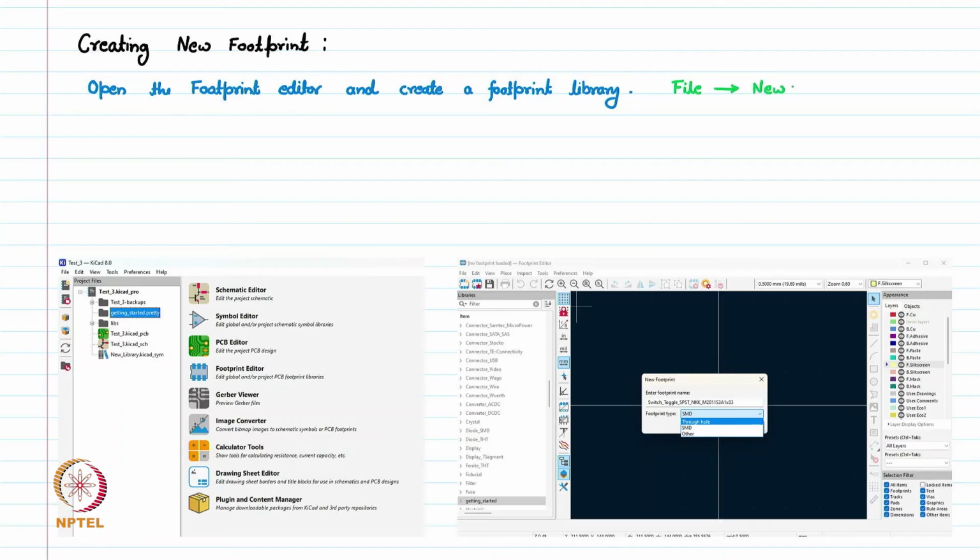It will ask you whether it should be global or a project library. Once you click on new library, you need to choose project, and you need to specify the name you want to give to this footprint library. The new footprint library will be added to the project library table.